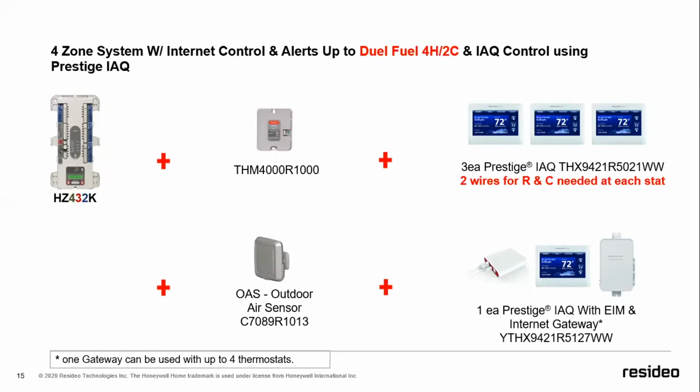And even though probably 95% of the time it's sold in a kit with the equipment interface module, in a zoning application, we have the ability to make transmit heat-cool calls from the 3 various zones that they're serving, and they'll be transmitting that signal to the wireless adapter, the 4000R.